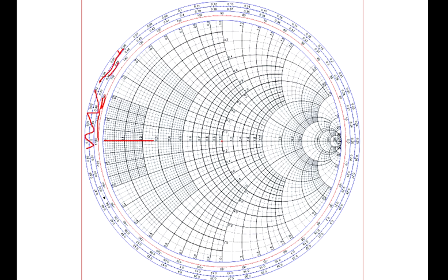And here's the axis that all the resistive values lie on. And for example, you can see this first circle that breaks out from that point. I'll try to draw it as accurately as I possibly can, and there we go. And here, for example, is an arc representing a reactive value. So here this is a value of 2, and it's intercepting a value of 1. So we have a normalized value of 1 plus J2 as an example.